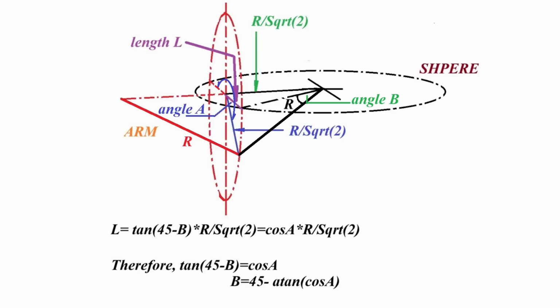In this drawing, the left-hand side represents the motion of the arm. The right-hand side represents the semisphere. The arm rotates on a vertical plane while the sphere turns on a horizontal plane. The common length, L, relates the motion of arm and the sphere. Although the line, L, does not actually connect the arm and the slot at the sphere, the horizontal distance traveled by the arm and the slot must be exactly the same.